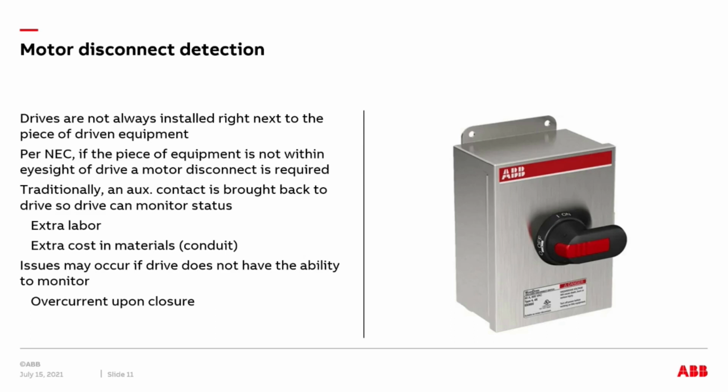So some issues may occur if we don't have the ability to monitor the position of that disconnect. If the disconnect is thrown in the off position and someone says to start up that drive, when someone goes to open or close that disconnect while the drive is running, an overcurrent event can occur.